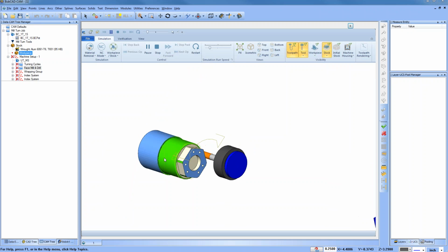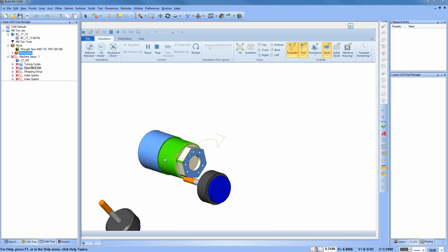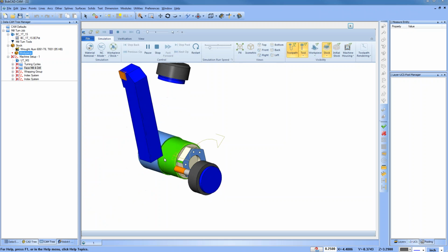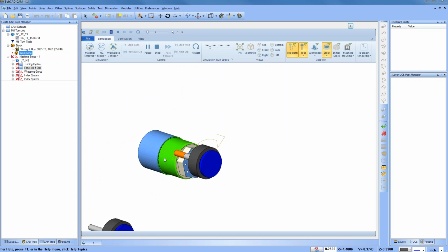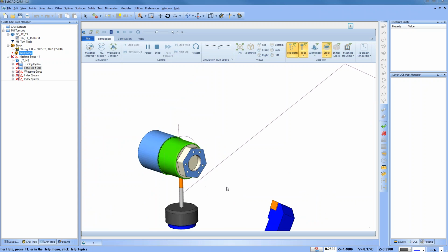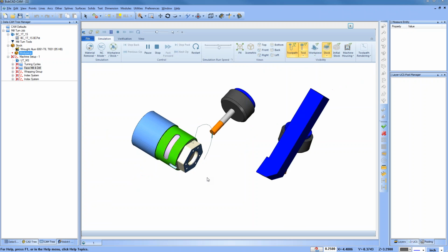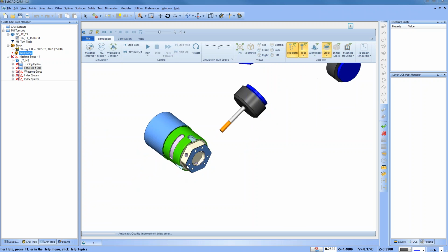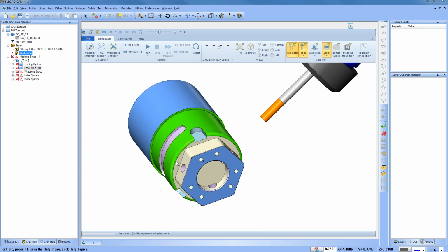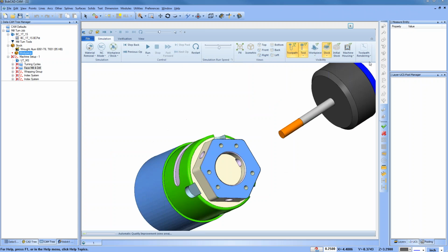So this is all the face milling and drilling. I drilled some holes. I did an open pocket. I did a circular pocket on the bore in the center. I'm going to do some chamfering where I'm going to come back and break the edges here. And that's what I'm doing on the face. On the OD, I have these slots that I cut into it, so I do a wrapping group for those. And then I use some index systems to come in here and cut these slots, and then I drill out some holes. Okay, so that's what we're looking at to do in this particular routine here.